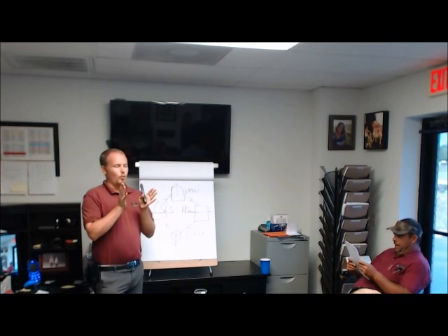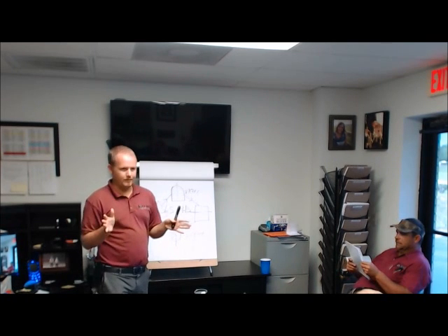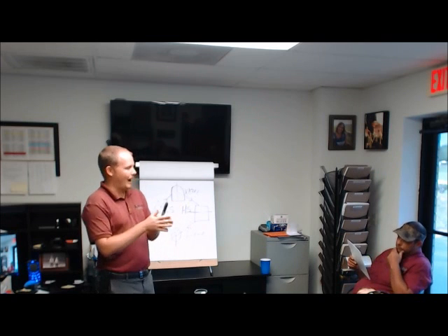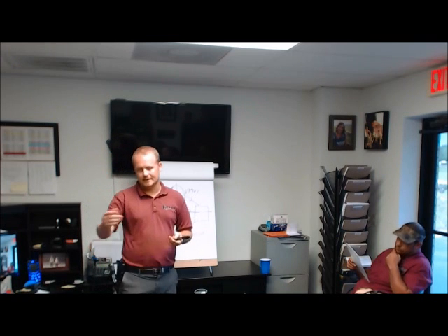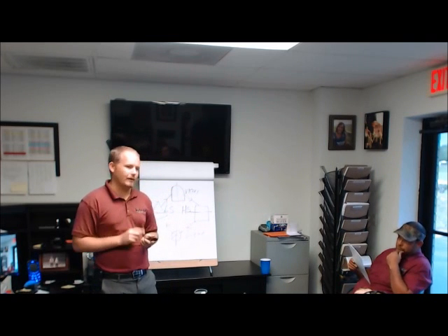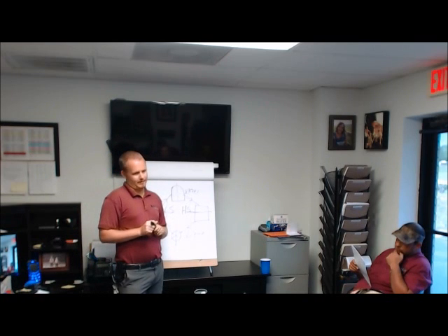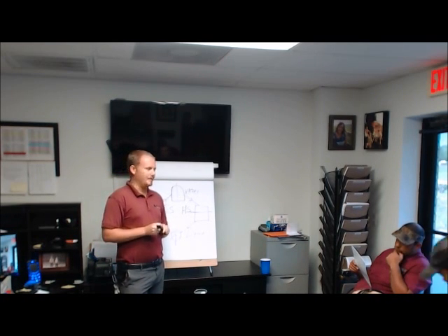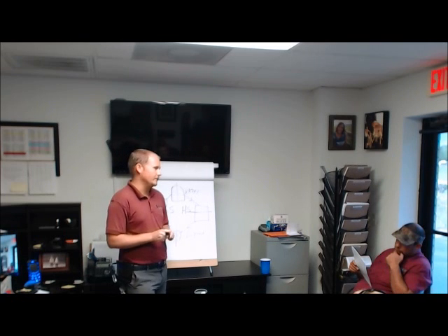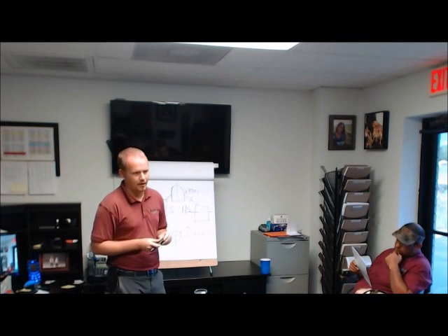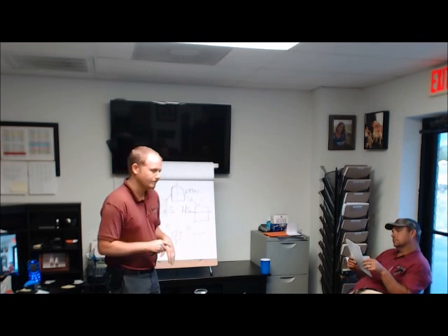So, what is the most common thing in the industry when your average AC technician says, "Hey, that system's low"? What is he usually saying when he says that? Saturation. He's saying the suction pressure's low. Yeah, that's generally what he's saying. It means he's hooked his suction gauge up on an R22 system and he saw that it read 40 psi, or whatever.